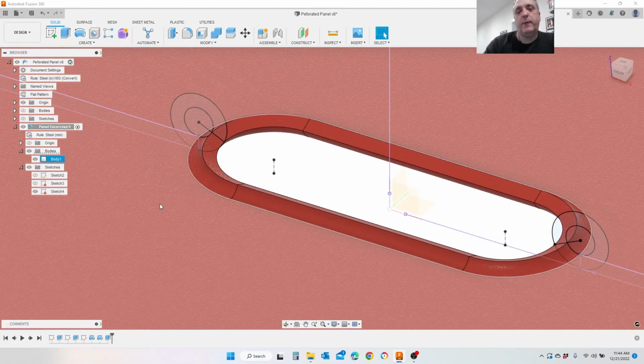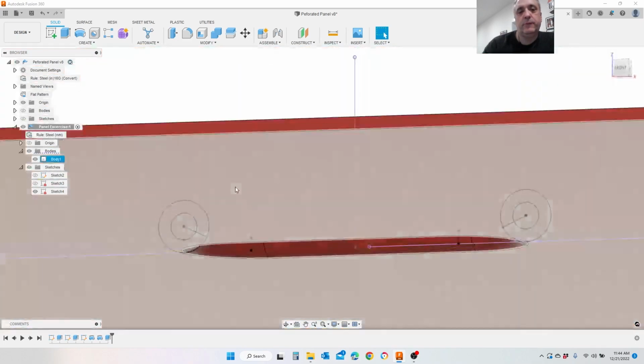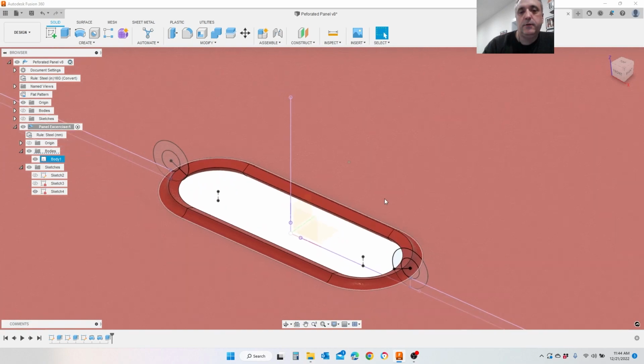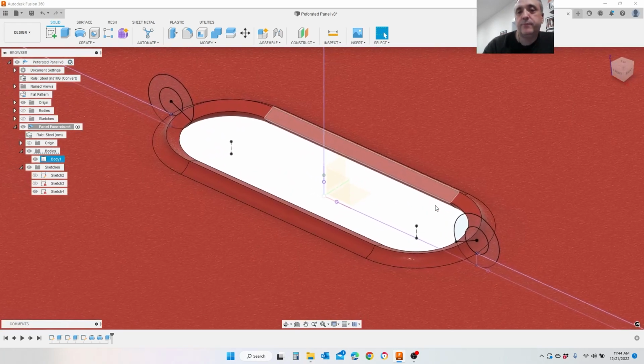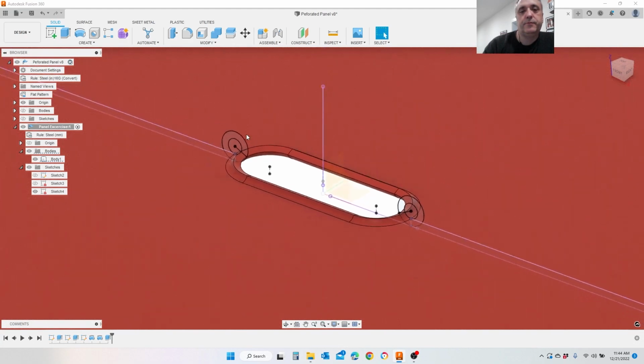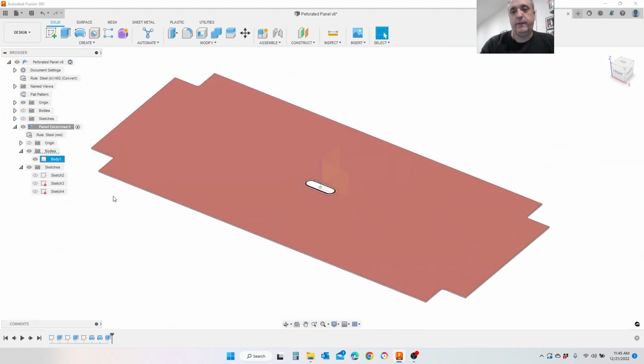So here you can see how I came up with that protrusion feature: by defining the circle, the radius of the tool that would be used to protrude it, and the angle at which I want it to end, which will give me some height off the top to give some grip. It also gives stiffness to this panel, and then they are revolved, and then I connect them using their two faces. So that basically creates that feature. So we have one in there.